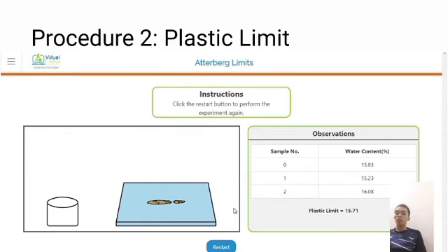If the can does not contain at least 6 grams of soil, add soil to the can from the next trial. Immediately weigh the moisture can containing the soil, record its mass, remove the lid, and place the can into the oven. Leave the moisture can in the oven for at least 16 hours. Repeat steps 3, 4, and 5 at least 2 times.